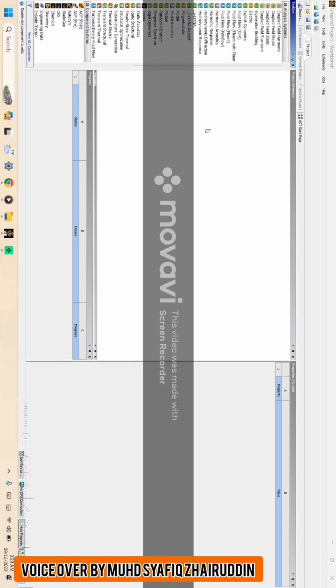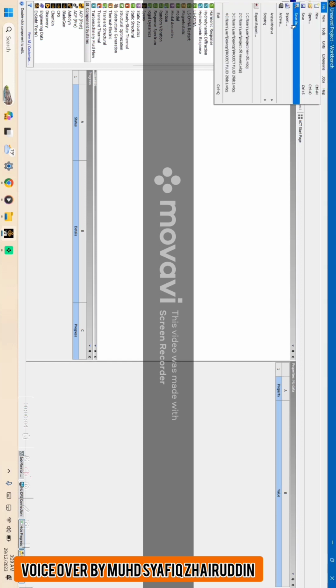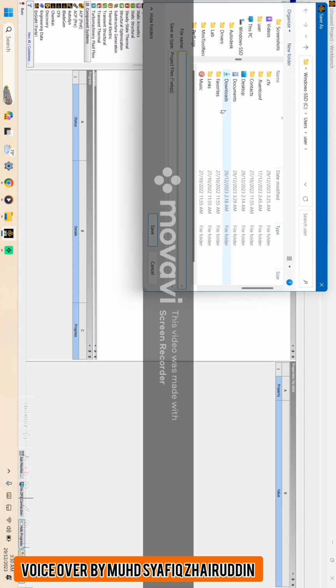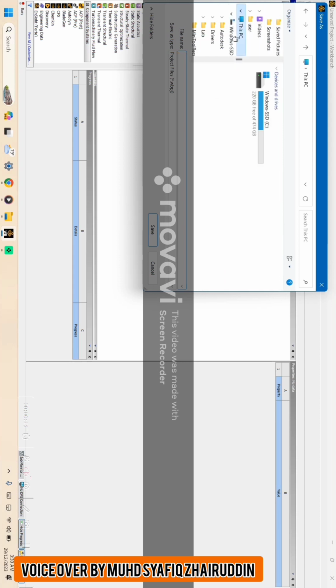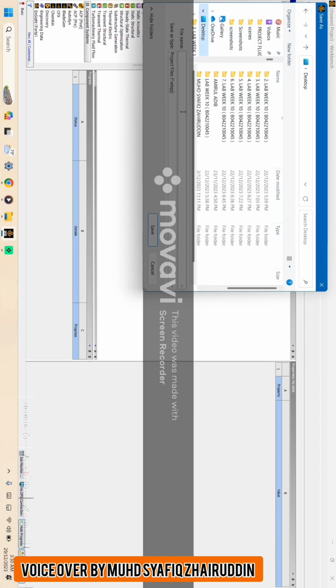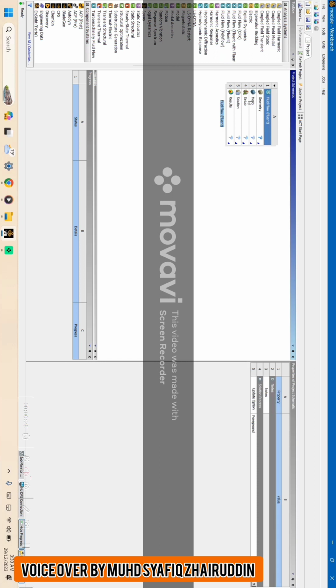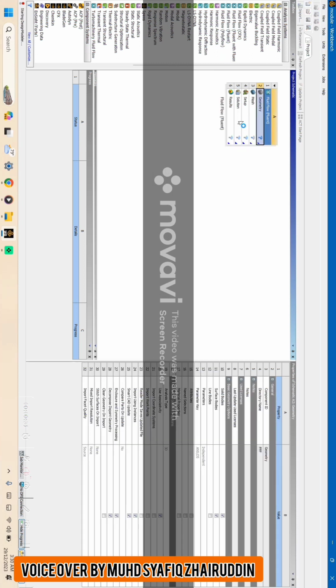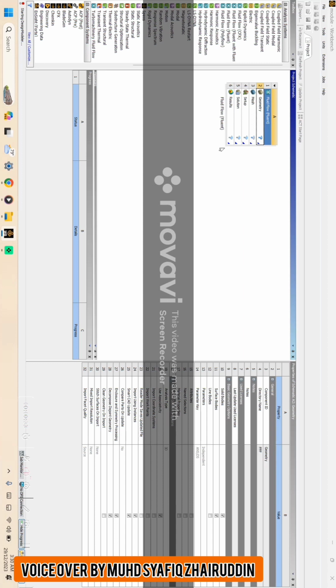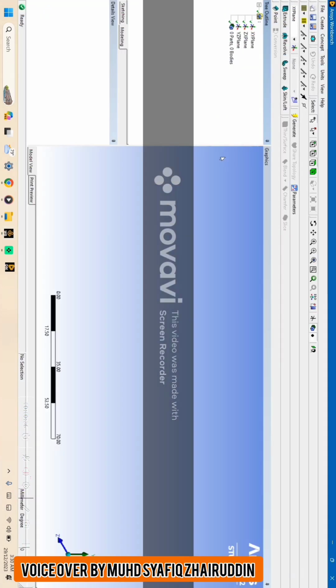Okay, I will show you how to use ANSYS for a CFD project. Firstly, open the Workbench and go to File and Save As, first on the desktop or PC, and I rename it as a module and then click Save. Okay, now click Fluent and click Geometry, right click and click New DesignModeler.